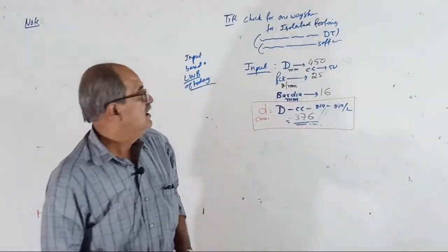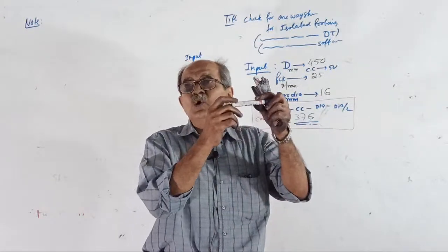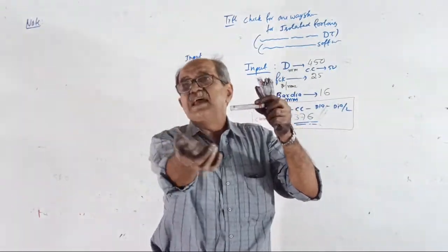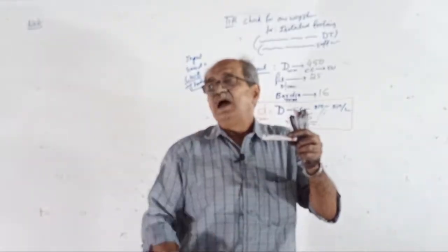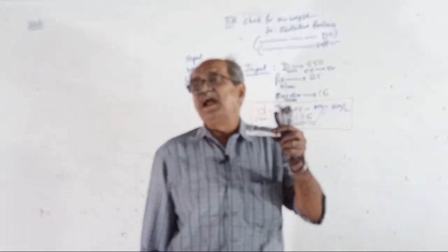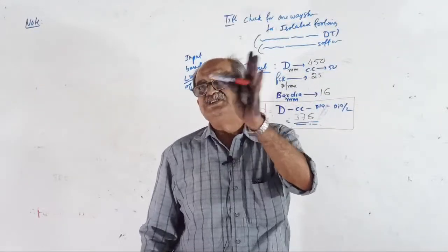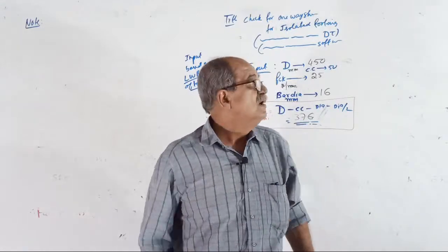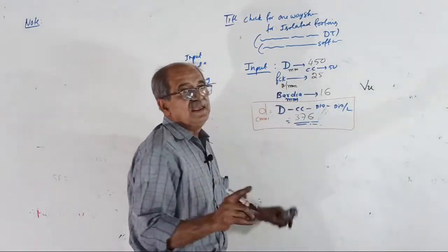Next. If you are doing manual calculation, you move by distance D, see the pressure value, and then find the shear force, and then without forgetting multiply by load factor and get the factored shear force. Finally you get VU if you are doing manual design, yes or no?